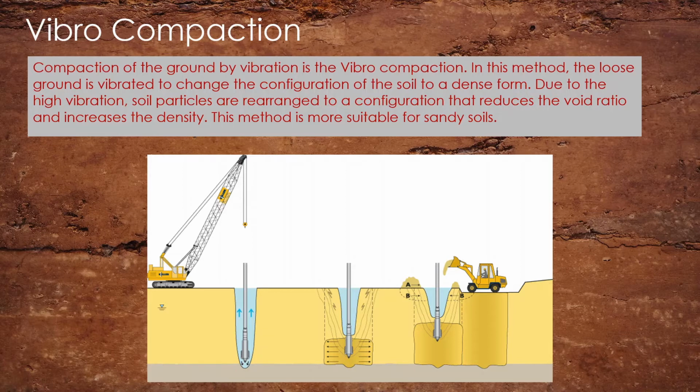density. This method is more suitable for sandy soil because in a normal soil with these vibrations, rearrangement of the particles will be very difficult. That is, generally the cohesive soil resists rearrangement. Therefore, cohesionless soil is more suitable for applying this method.